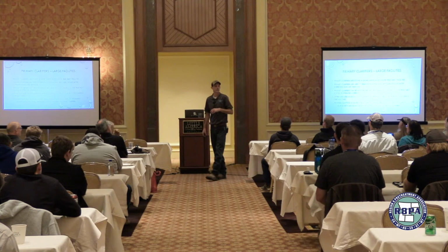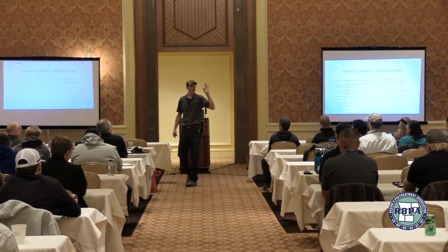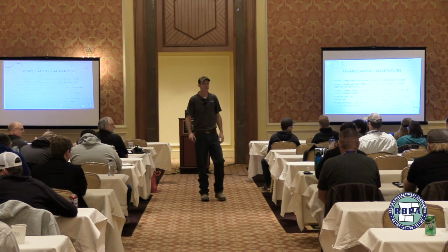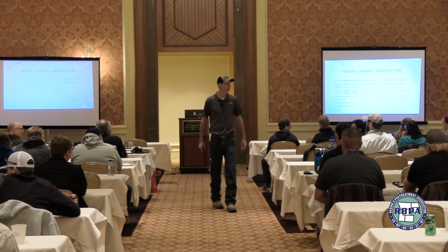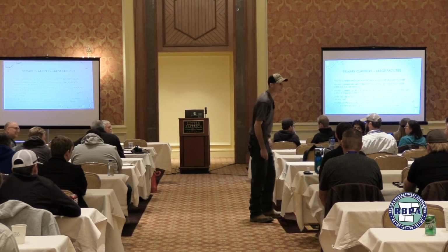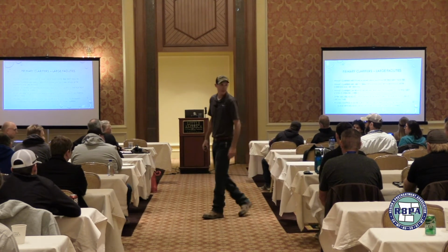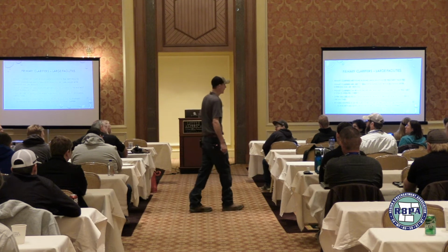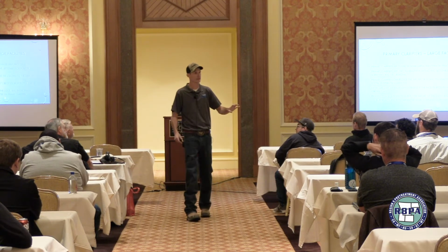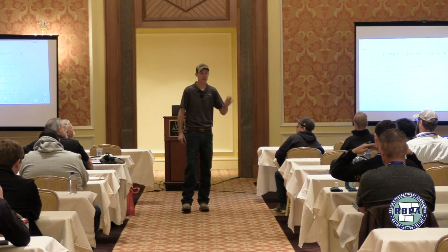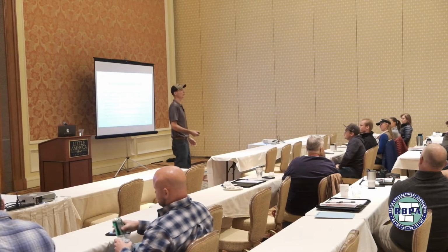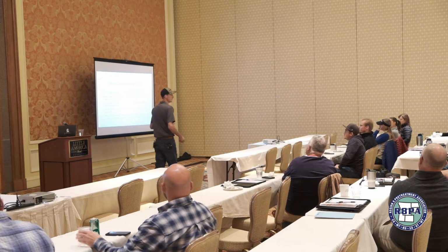130 million a day. 3 primary clarifiers. Now, every drop of that 130 million goes through those clarifiers, right? What happens if I have a huge FOG load one day? Knocked offline. They are knocked offline. Now what? Now my primaries, my preliminary treatment. Headworks is still running. Preliminary treatment's gone at the primary clarifiers. And now I'm running everything straight into an A basin, right? Not good for a big plant. I mean, you are violating permit limits within minutes.